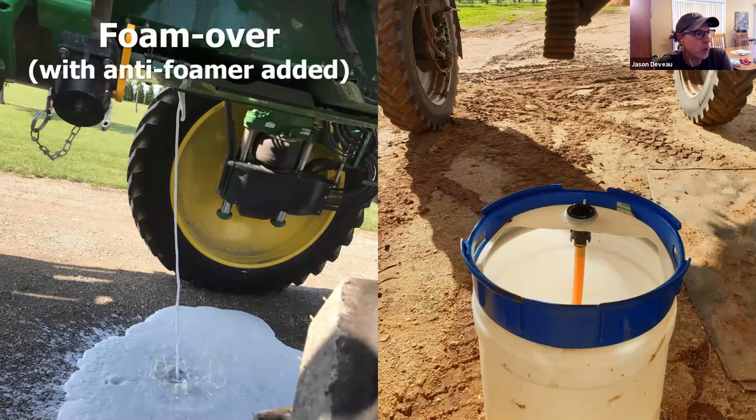I did this. I'm going to fess up. We were filling a field sprayer with, of all things, dicamba. It was for a volatility study that I was part of, and we used anti-foamer. We did everything we were supposed to do, but what we didn't do was back the agitation off as the sprayer was filling. So we had full bore killer agitation with only half a tank full, and it frothed up like a milkshake and foamed over. And boy, what a mess.